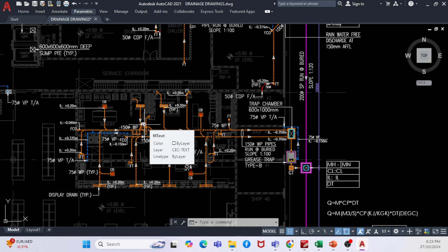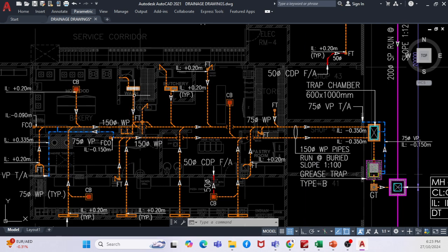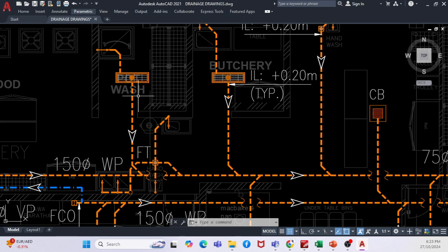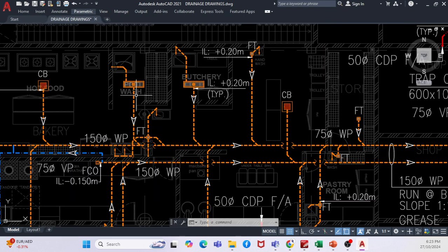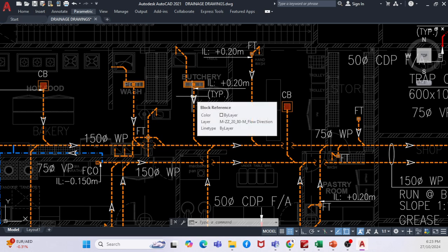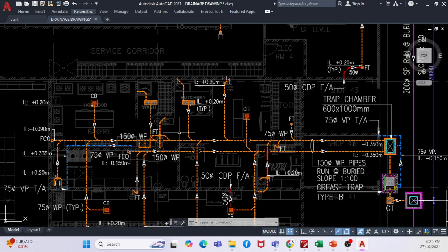Okay, so you can increase the waste wherever you can do the analysis. Say, for example, I am expecting some waste, some smells from here, so I can use the vent pipe from here. You can connect a vent pipe. You can provide one vent pipe to this area. Just adding one pipe to this area, adding one pipe to this area, right? So as an engineer to engineer, you can decide. It's not simply to follow this drawing, right?